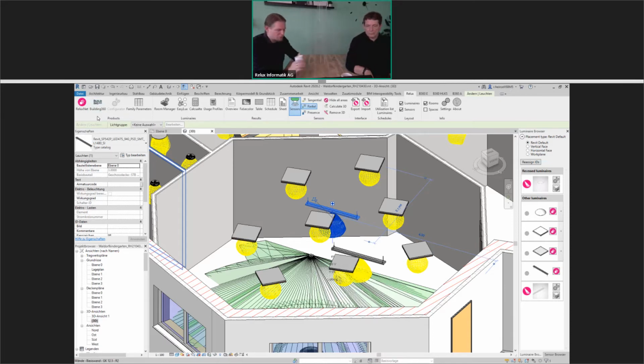Yeah. This is also what we have learned, that a lot of lighting designers work with generic products in the beginning, which are not specified, to just have a placeholder for a luminaire or to have the first ideas of a luminaire on this position. There's a need for generic luminaires, and we have the possibility with our add-on to work with generic non-manufacturer related products by linking a real product into a 3D symbol, in order to do calculations and have estimations on brightness and on dimensioning of this light.